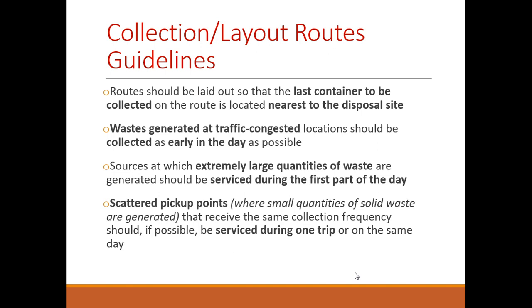The sources at which extremely large quantities of waste are generated should be serviced during the first part of the day, particularly in a place like Trinidad and Tobago, where there is a lot of heat. You don't want to leave that large volume of waste in that heat for decomposition to begin to take place. You also want the containers to be empty at the start of the day, because we know that waste will be generated during the course of the day, so you would want those dealt with in the first part of the day.